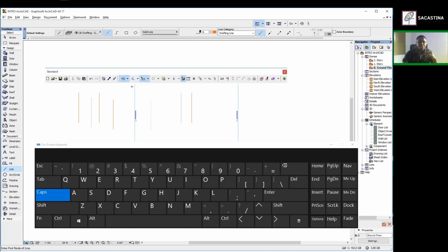Special snap point, when it is off, you cannot identify a point for a particular thing. For example, what you see here is the automatic grid line sign, but the snap point may show you the center of a place. It will be difficult for you to identify. Now look at it very well. The symbol is also there. Now let's activate it. We've activated it now. Now go to this line. You see it has given us a center point line for us to work with. That's one of the things that particular one does.